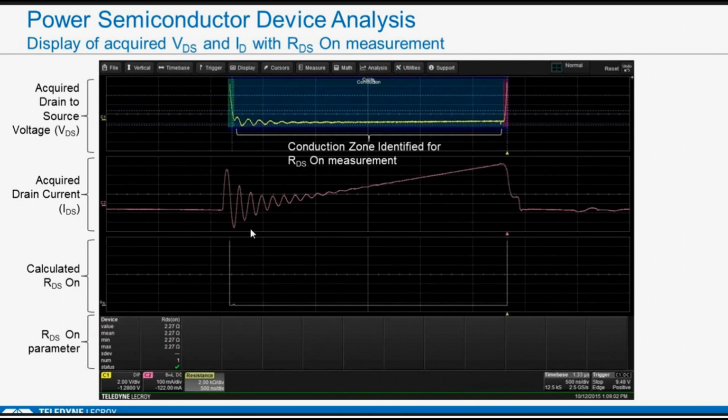If I really wanted to focus in on the conduction loss, what I want to do is get that zone. I really want to overdrive my scope. The problem is most scope front ends are not capable of being overdriven in a good way. They'll fail very quickly. The days of the unbelievably great analog front ends on scopes, if they ever existed, are no longer with us. And so typically what people do is they'll use this differential amplifier, the DA1855, which really just has an awesome analog front end, and it can really be pushed hard and overdriven, and it has other characteristics too that make it ideal for this measurement.